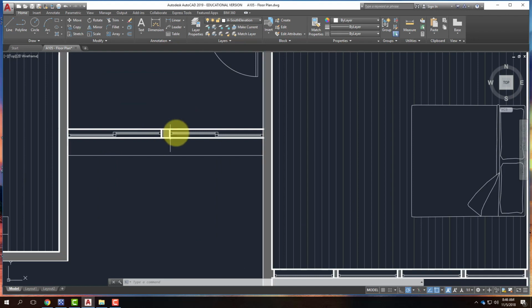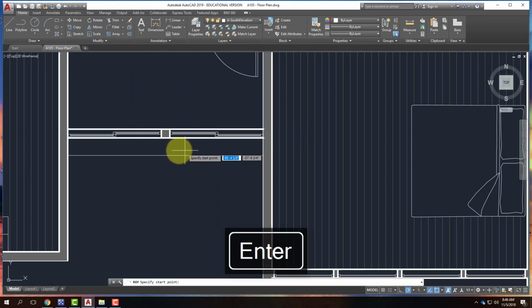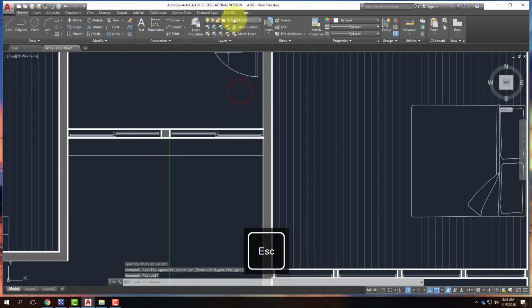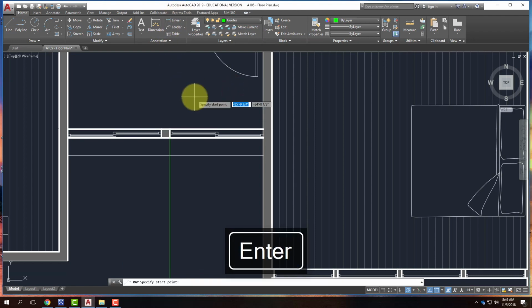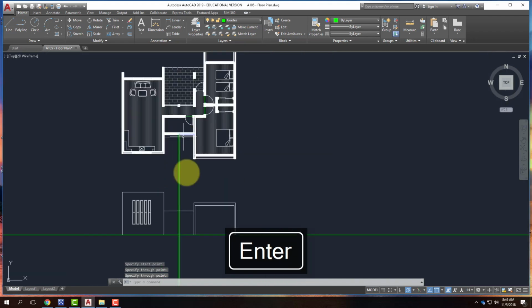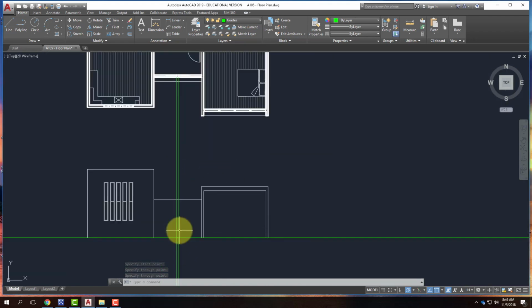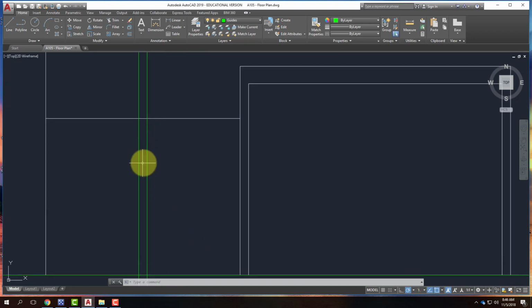Here, I have a post in the center, and I have 2 sets of windows. So same thing, I would type ray. And whoops, this was not on the guides layer. There it is. And we could go back to the guides layer. I typically delete these rays after I've used them because it can get rather cluttered when you have lots of these rays coming down. So if you stay clean without too many of them, that can really help.